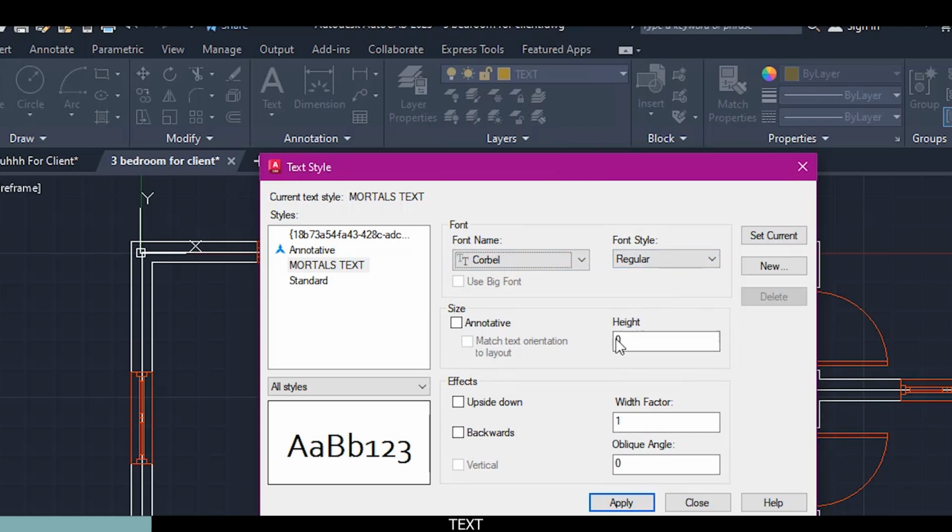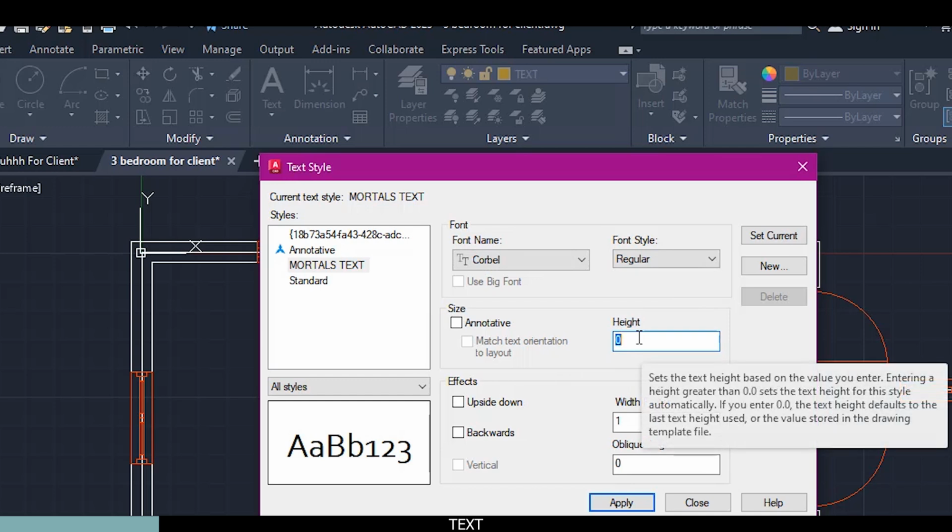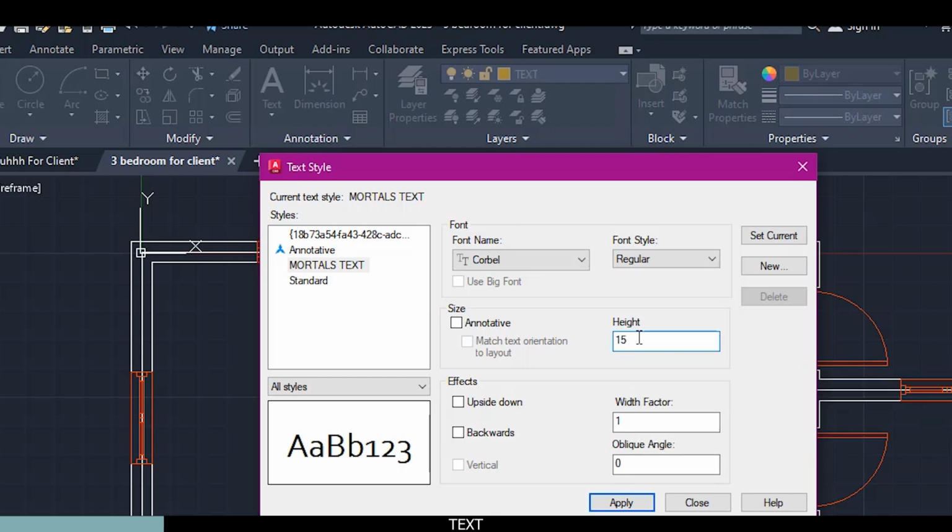And did I just say 10 years? I mean 10 days. So now I'll double click on this text height and put in a text of 159 millimeters. Don't try to dig deep into that number. Now, normally the text height metric should be around 3 millimeters or 3.5 millimeters, but because of the version of my AutoCAD, that doesn't work. You will see what I mean.